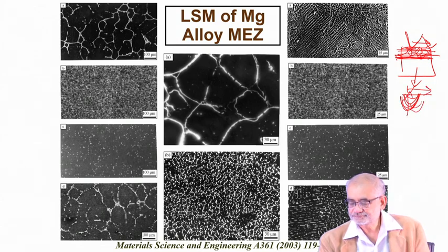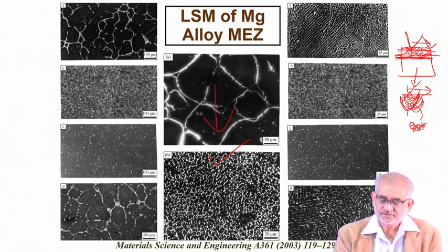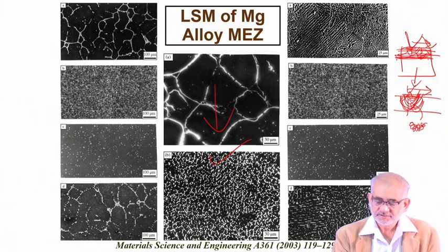So now the solid-liquid interface will recede to the surface, and when it recedes, this region becomes solidified, and this solidified microstructure will be extremely fine. So the grain size will be extremely fine, and this is exactly the effect we are seeing here. So from this microstructure, purely by surface melting up to a certain depth from the surface, we can convert the surface microstructure from being so coarse to so fine.